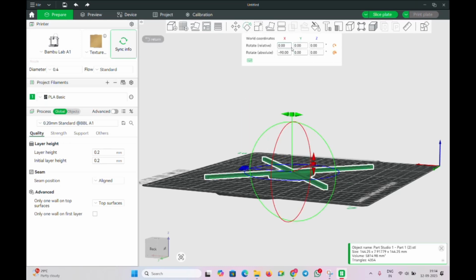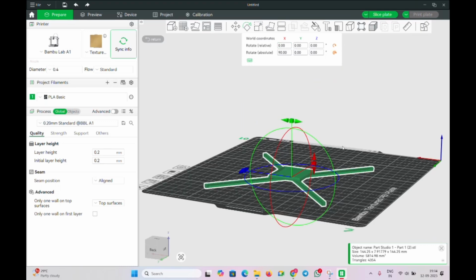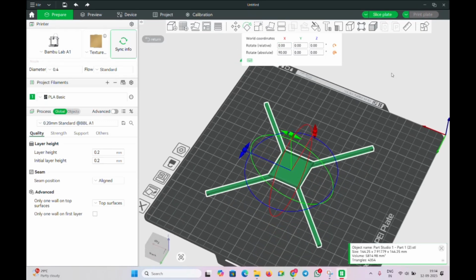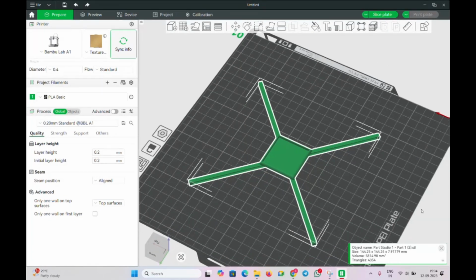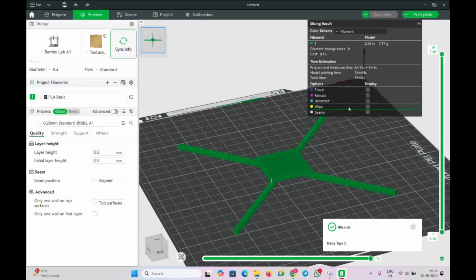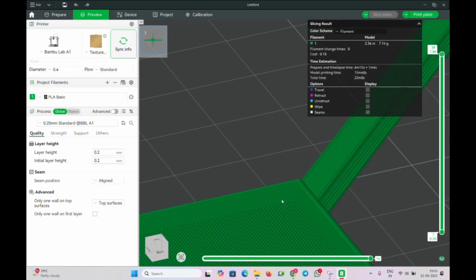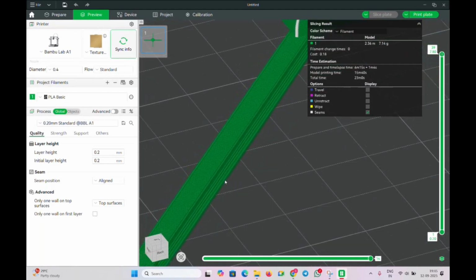Now to change the orientation of this project, I will click on change orientation, and now you have to do some experiments to see what orientation will fit best for the geometry to be 3D printed. In my case, I already found it, placed it, and here we go. At last, the only thing required is to slice this thing. So by clicking on preview, I will get all the basic dimensions, weight, and calculations of how much the weight of this complete part is and how it will be printed in layers. You can see the layer patterns in the given dimensions as well.